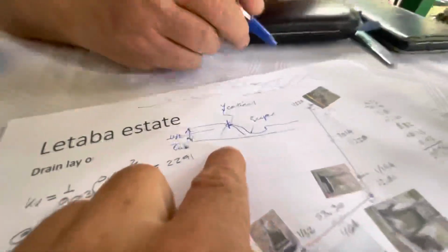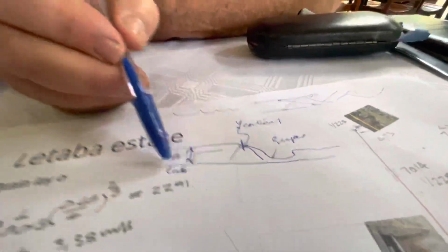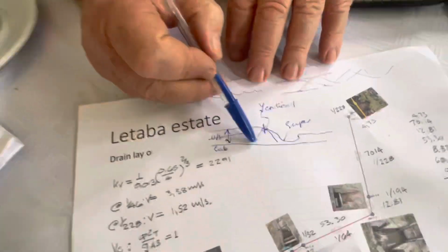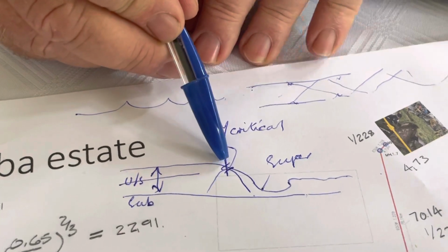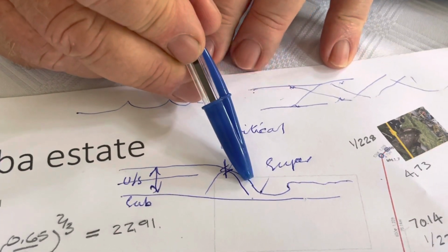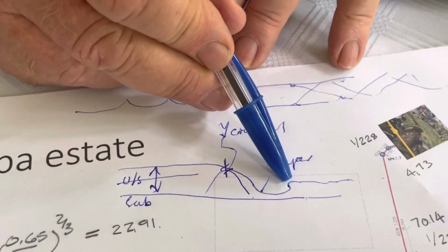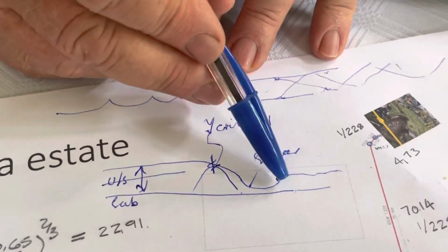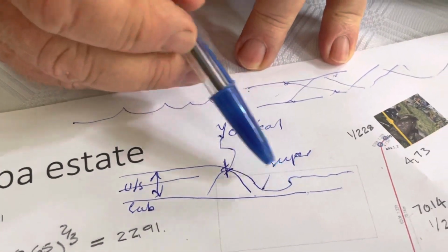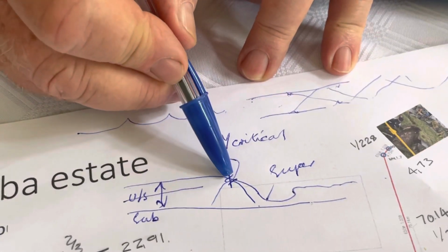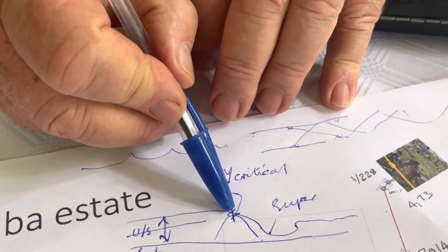And over here you were drawing... And this is what happens if you now have a channel and you have an obstruction in the channel, like a dam wall. Then the water dams up behind it and it flows slowly, and then when it goes over that crest, it accelerates, and then you will see downstream you will have a whole lot of turbulence. So this is what's called subcritical flow, this is what's called supercritical flow, and when you go over this bump you have a constant depth, and that's where you can measure the depth, and you can get the velocity, and then you can get the discharge. So that's like a control point on the system.